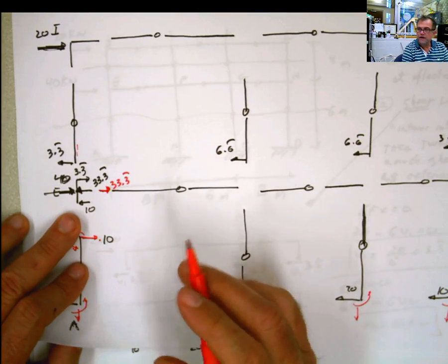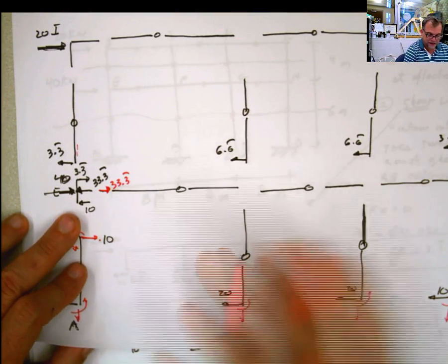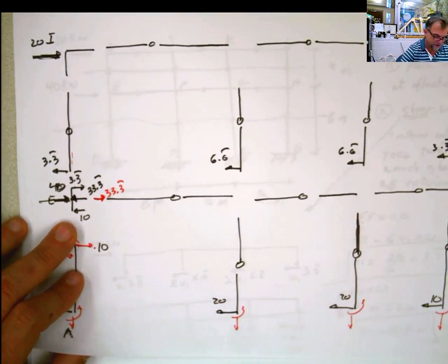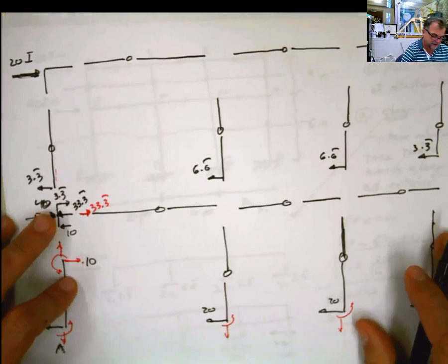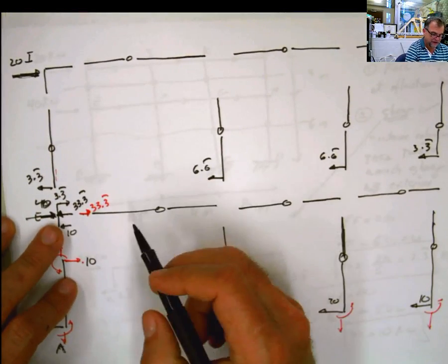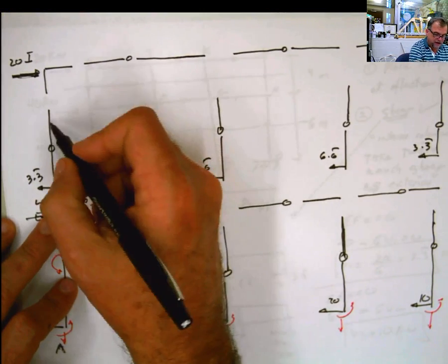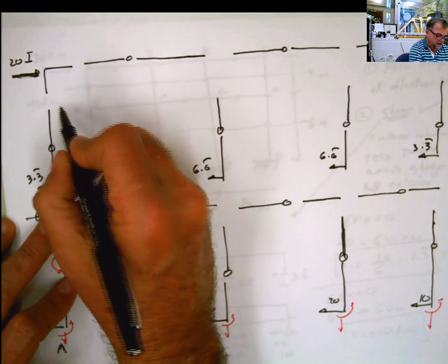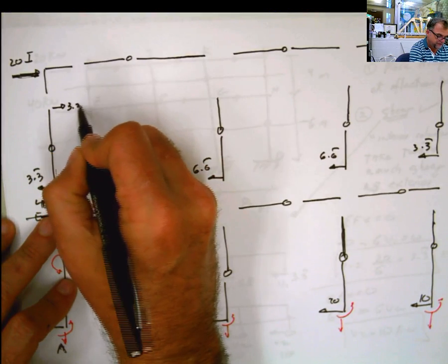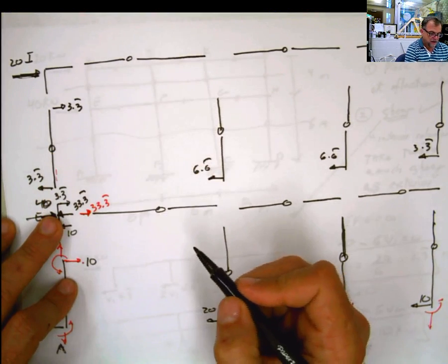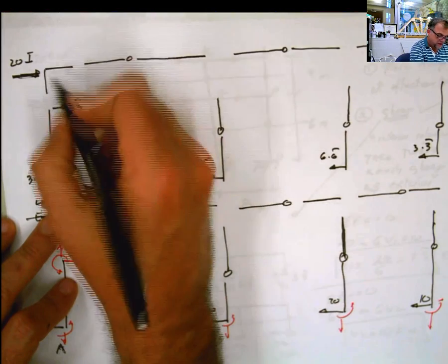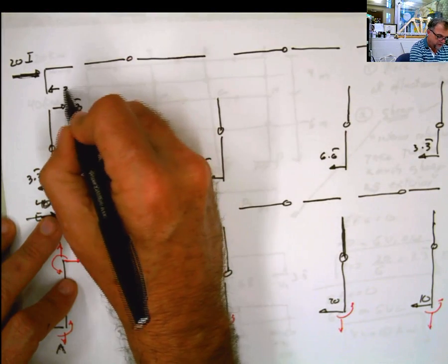This is like completing a structural Sudoku. The only thing is that they don't have to add from 0 to 9 in every single part. So now I'm gonna go here. This is 3.3. I don't have any other force here, meaning this part here is gonna be also 3.3, like that. And this one is gonna be transferred to the joint as 3.3.